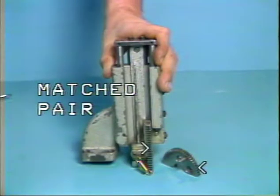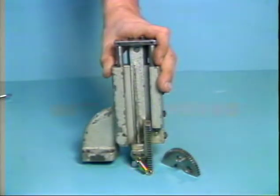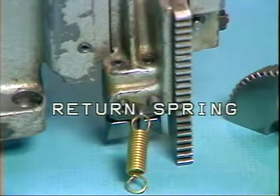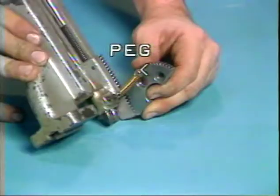This is the return spring for the half-circle gear mounted on the friction clutch. The purpose of the return spring is to assure the friction clutch and the half-circle gear are pulled back to its original starting point in each cycle. The return spring is attached to a peg on the half-circle gear.